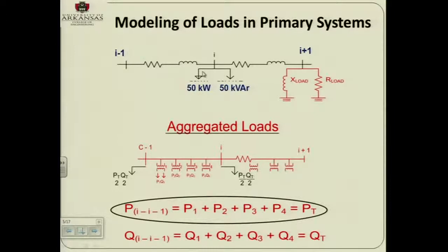And so here is basically how you model the loads at each node. That's what you did for chapter 5, so this is taking the homework that you did for chapter 5 to the next level. You need to go and correct the mistakes that you had in that PSPICE. I don't remember if the resistance and the inductance of the feeder are the same. I may have changed the feeder, so you have to change those numbers.